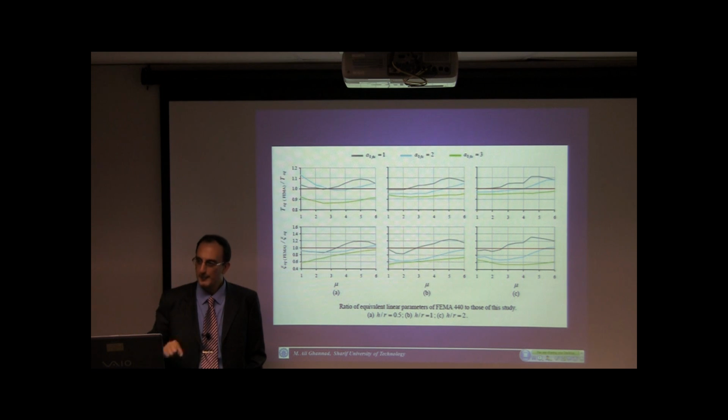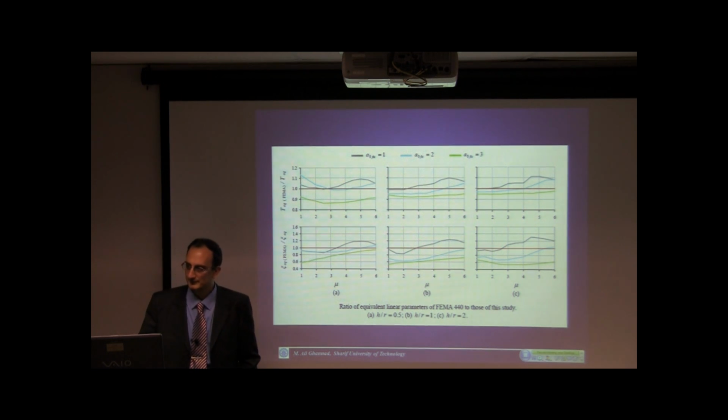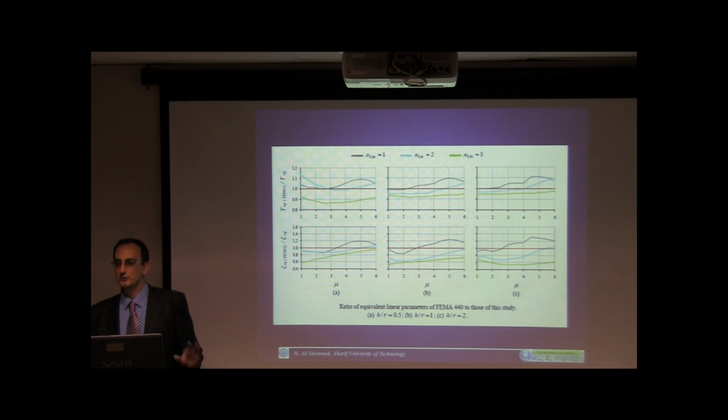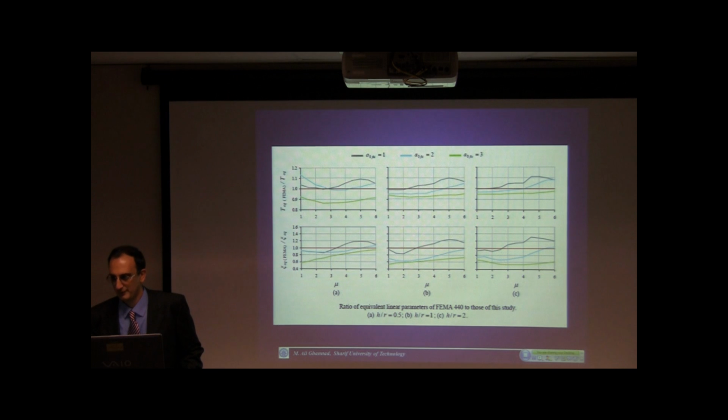Okay, so you're looking at radiation values. Yeah. But we just mentioned that soil gets to be nonlinear. Before the soil gets nonlinear, you have a lot of scattering values. You don't consider that. Yes. And when the soil gets nonlinear, there is an incredible amount of energy wasted there. You don't consider that either. Yes, you're right, completely right. As I said, you are completely right. These are very important factors.